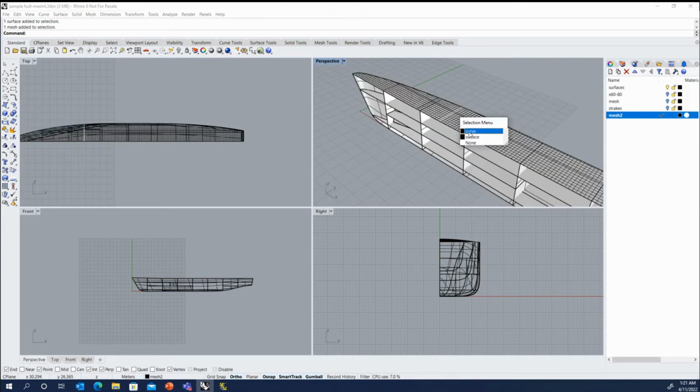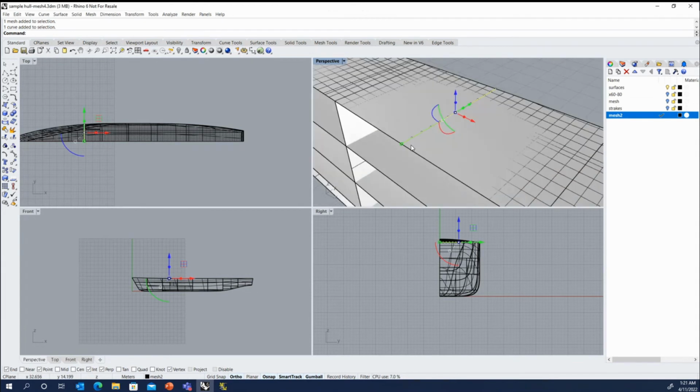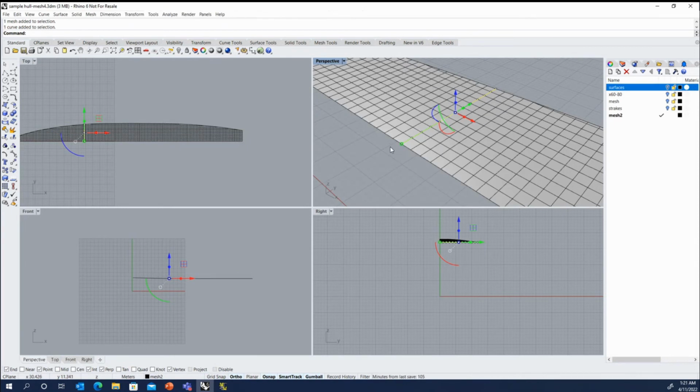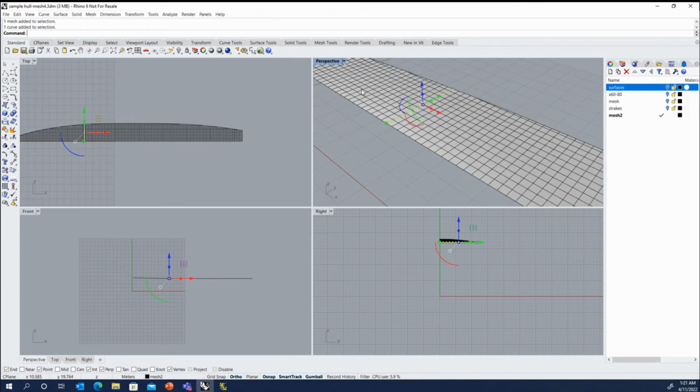So, and the resulting curves at the end here, you can see it has points, let me turn off the surfaces, replaces the original curve with a polyline. So basically, in the beginning, when there was that pause, it was taking all of the section curves and converting them into polylines with the appropriate spacing. And then afterwards, it went through and joined them all into meshes.